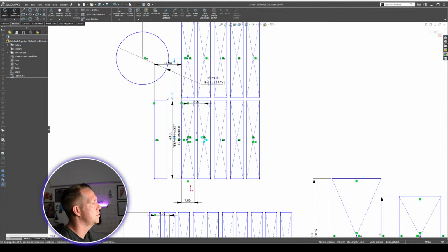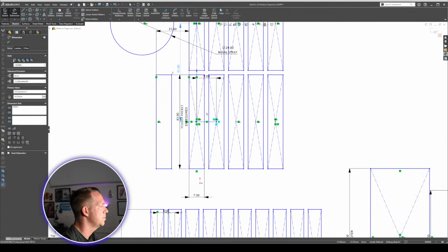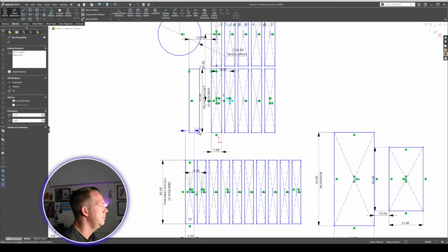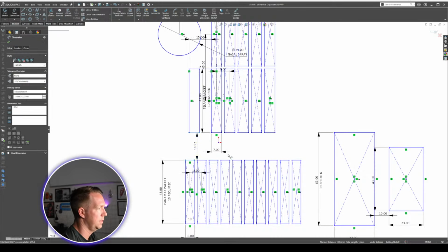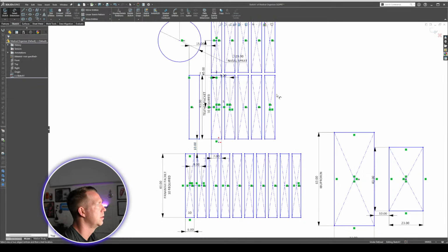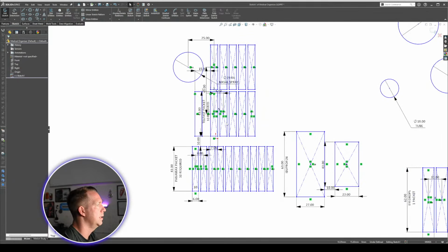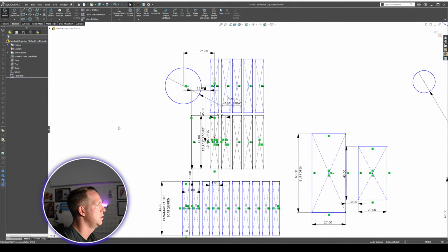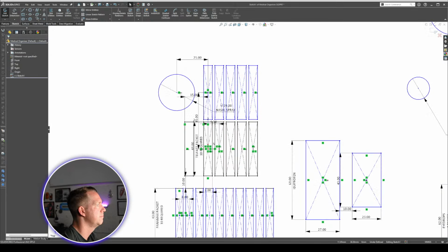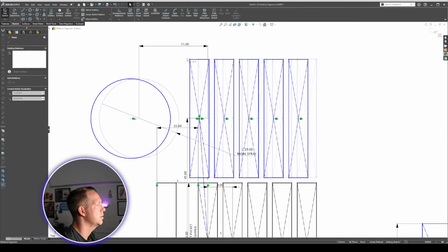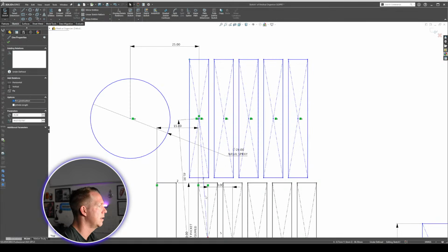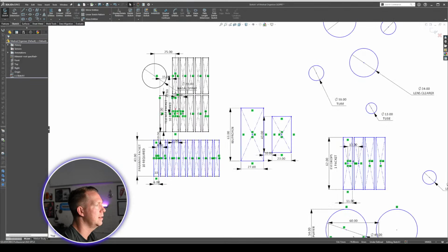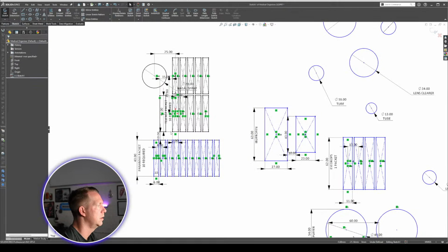I'm happy with that spacing. I want to do a little bit extra spacing on this side. So let's put 10 millimeters in there. And then let's put this one on the origin. So it's going to lock that position. This position here is not locked because of the construction line. Let me make that vertical. And then let me get this side and lock this one in.